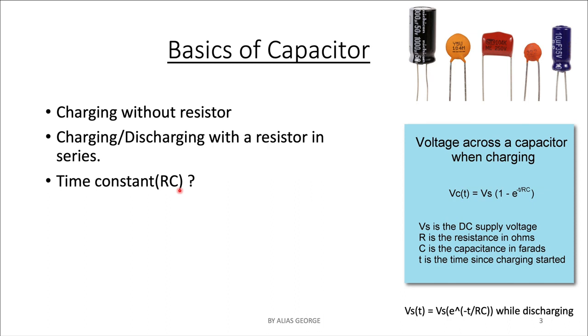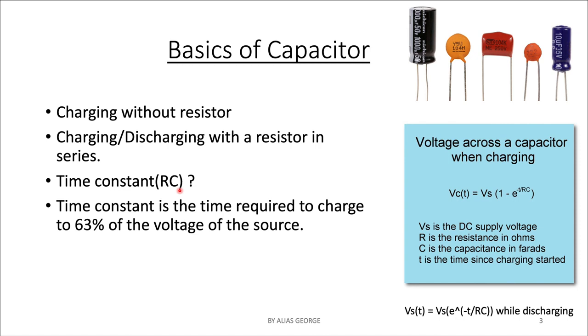In the previous illustration we have seen that for the charging case, if we increase the RC constant, we can increase the duration of that charging. Similarly in the case of discharging, if we increase the RC constant, we can make the discharging duration longer and longer. This is the idea you need to get from this slide. So that explains all of this.